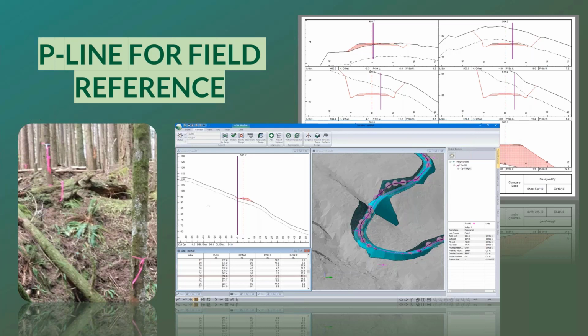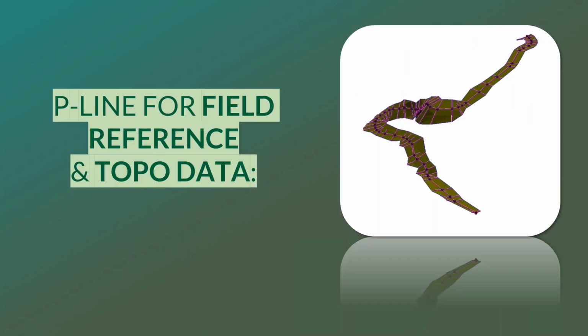Then the other side of it is it's nice to know where you should be. So in the two images to the right, we can see the purple line showing up in those cross-section views. That's representing the P-line location, but we can see the designed road center line is actually off of that. So it's useful for giving us that relative measurement to those stations in the field to know our offsets and to help stake and build what we intend to build.